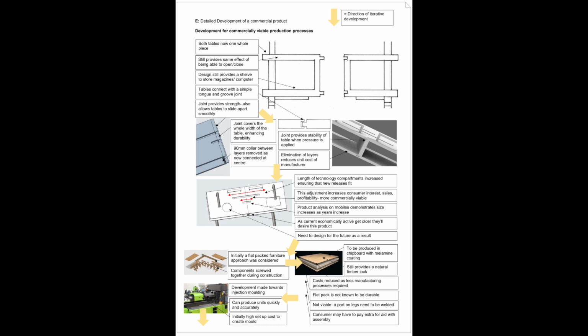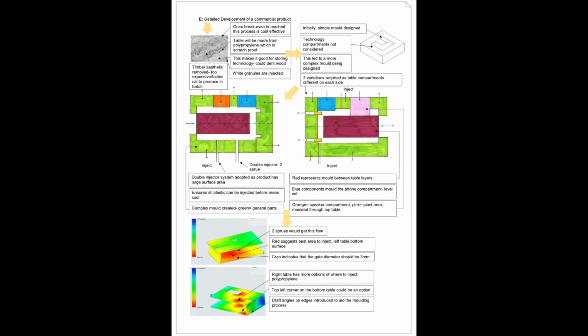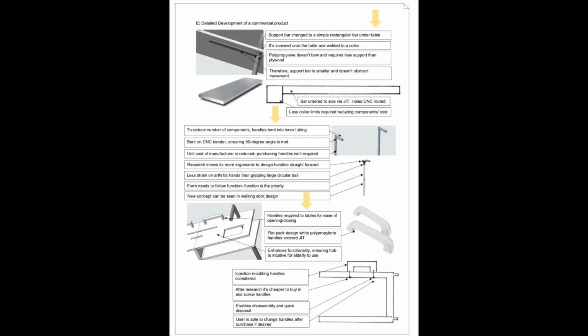Some consideration is given to the change of materials and production processes while still retaining the functionality of the design. The use of mold flow analysis indicates a highly competent analysis of data and the need for a complex mold with 3 injection gates. Modifications made to tubing suggest an incorrect process for creating holes and the radius needed for the bending of the tube to 90 degrees.